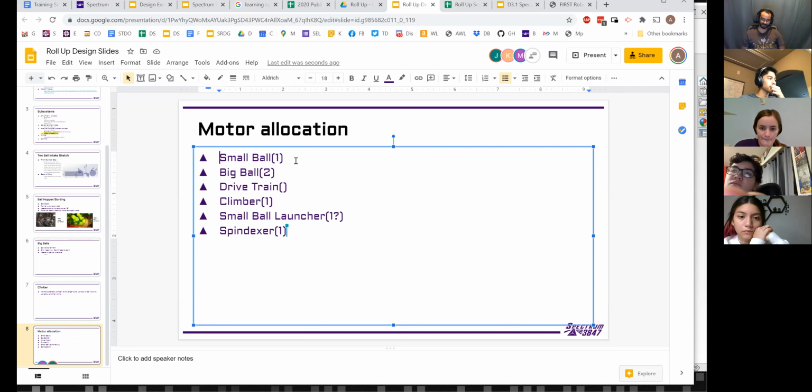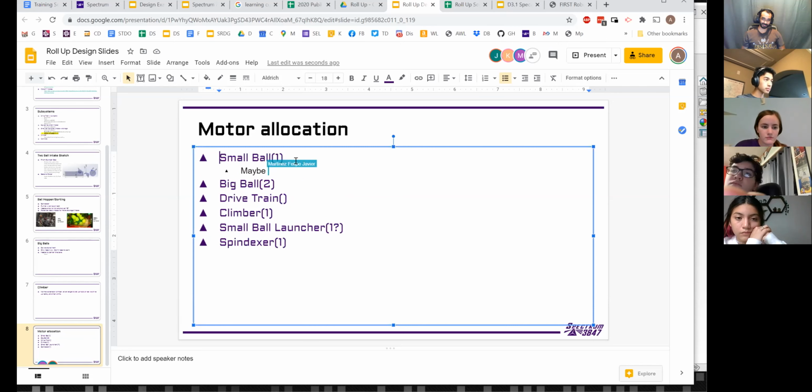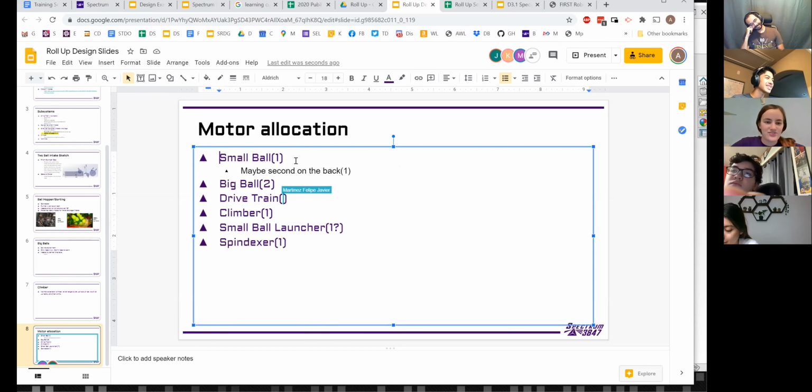You could end up with a back intake, which would be a 7th. And then you have 4 in the drivetrain, which is 11 if it's a normal drivetrain. 8 in the drivetrain if it's swerve, which is 15. That's a lot. But it could be swerve. We have the motor allocation for it, even with a back intake.